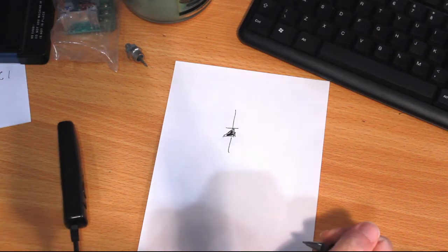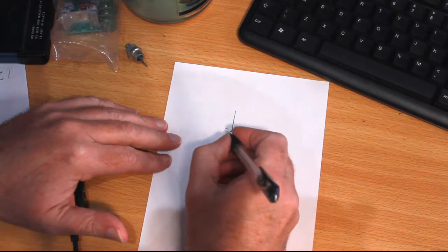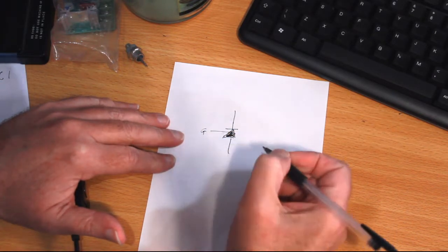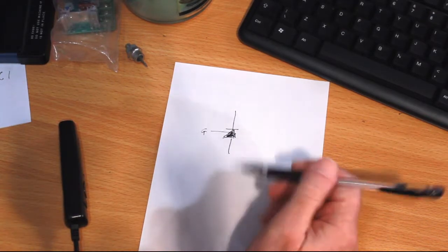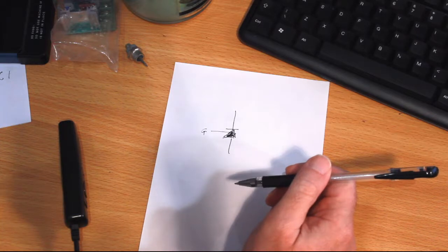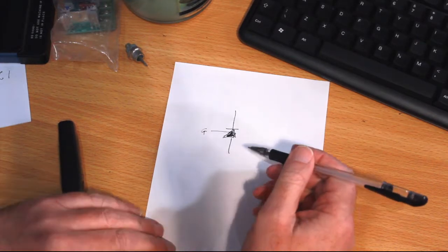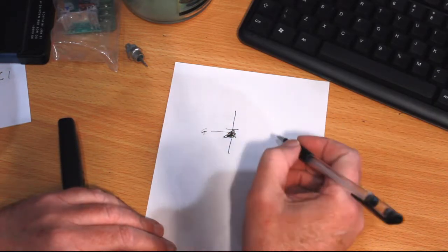Okay, so what have we got here? We've got what appears to be a diode. It's not, because it's got a gate there. When we put a pulse on that gate, this thing conducts, and it stays conducting until the current through it passes to 0. I'm not going to do the AC waveform again because the drawings are pathetic.